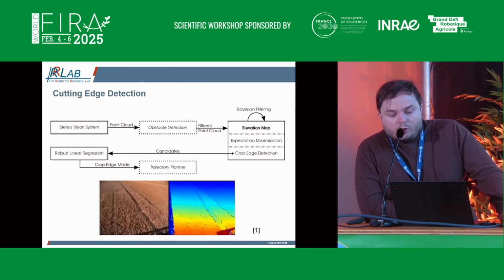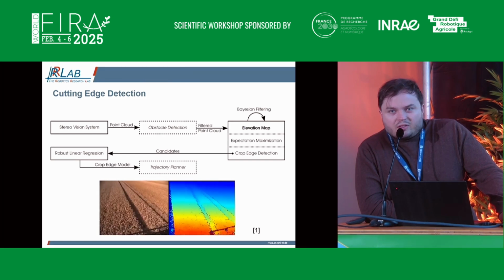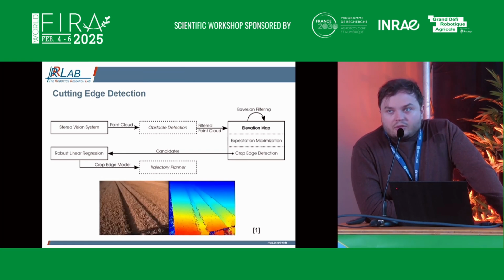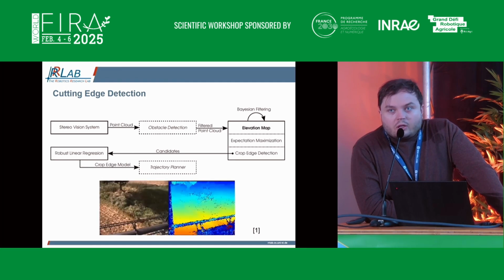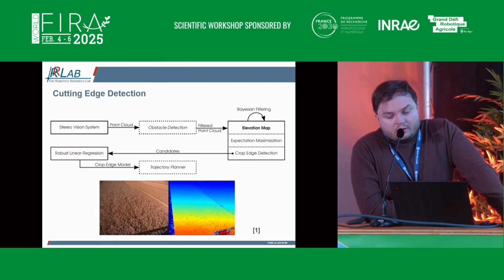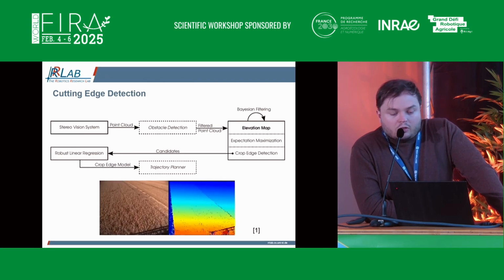And here we did a couple of different things with this, because the sensors are always tricky to use because they are noisy. The values that we get from them, they're not necessarily what we would always expect. So here there was a lot of Bayesian filtering involved. That means Kalman filters and whatnot to denoise the sensor data, so then it could actually yield the behavior that we wanted, which was also highly dynamic in this case. So yeah, that's a little bit of what we have been doing before,